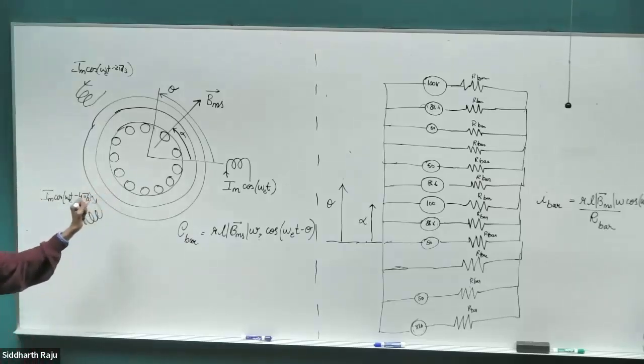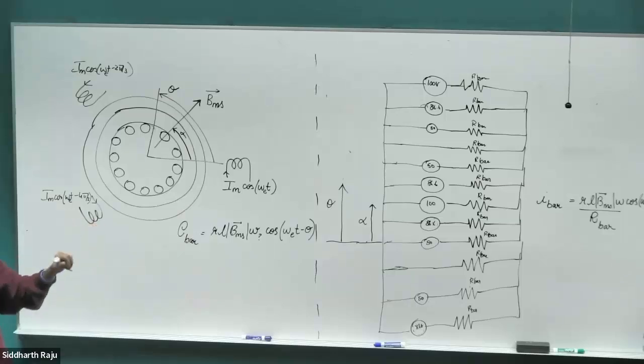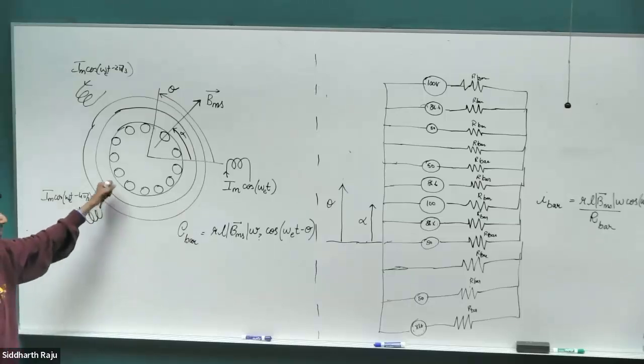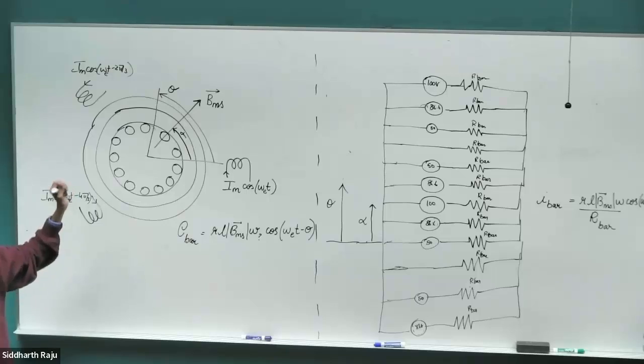Right? So we have already seen it for a permanent magnet synchronous motor. The same structure is retained for an induction motor as well. The replacement that we do for an induction motor is where we take out the rotor, which has magnets on them, and we instead put the squirrel cage structure, which is just a bunch of shorted copper bars in case of high power motors, and in low power ones typically aluminum bars, with some end rings which are shorting on both sides. Right? And there are no magnets on the rotor.